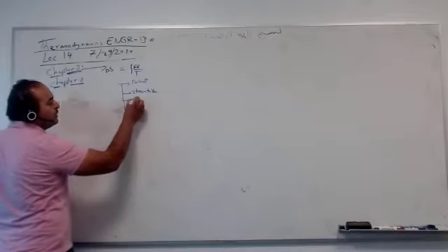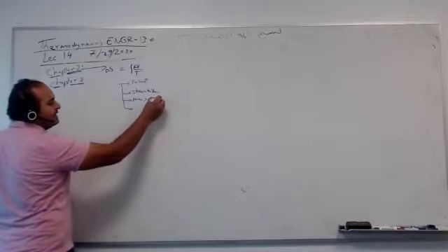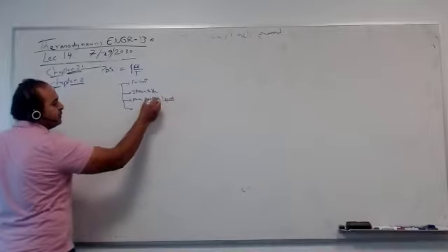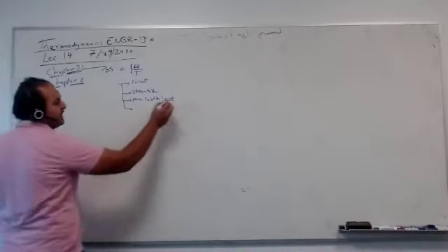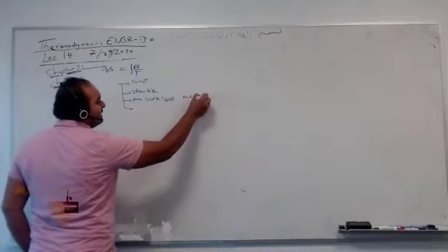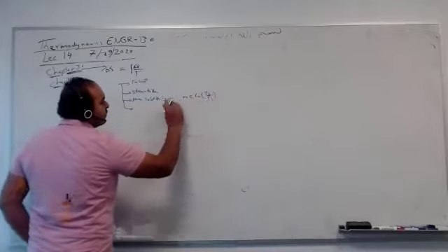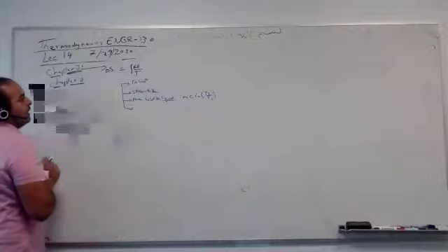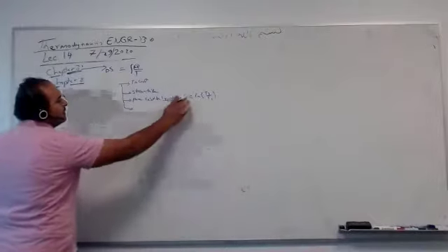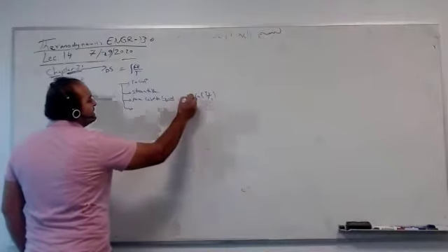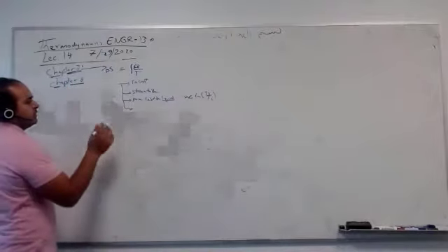If we're talking pure solid and liquid, it's so simple, just M C ln T2 over T1. If we're talking about specific entropy, without mass. With mass, it's the total entropy for this solid or liquid.